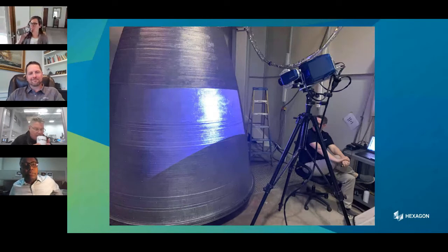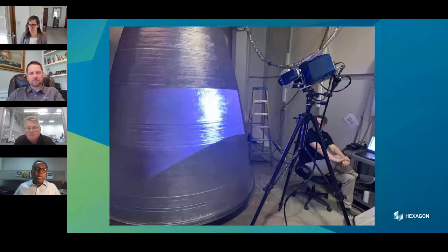Absolutely, Giles. It goes back to the same thing. What do I want and how do I get it, and did I get it, right? So without these measurements, we wouldn't have known where we are at the end, right? We did the simulation, we did the process and in between measurements, but at the end, it matters what we ended up with. And not only that, the second important aspect of the scanning measurements is when we take it to the next step for machining of the part, final machining step, it's absolutely important to know where the part is, what condition it is.